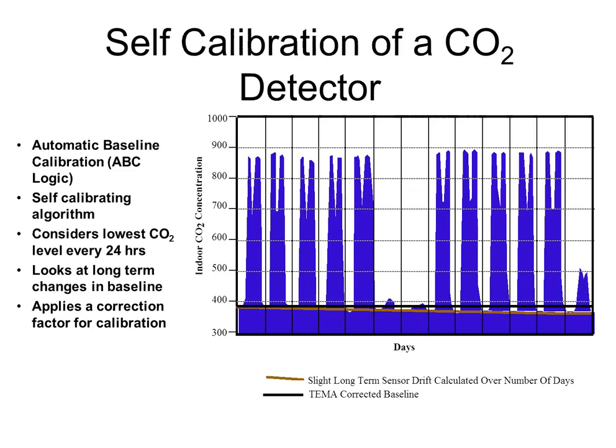The way they do that, and there's two manufacturers that make these CO2 engines, if you will, and they put them in everybody else's plastic housing with their logo, and custom brand them and all that. There's two people making this engine, and basically what they have is this thing called automatic baseline calibration. As long as your building goes unoccupied for at least 4 hours a week, which is almost every building in the country, right? At least 4 hours a week, no one's there.